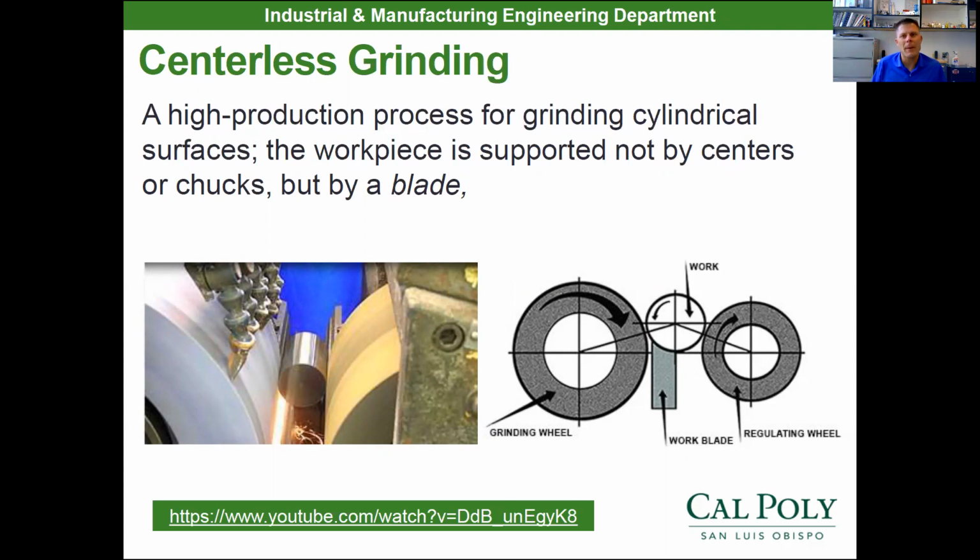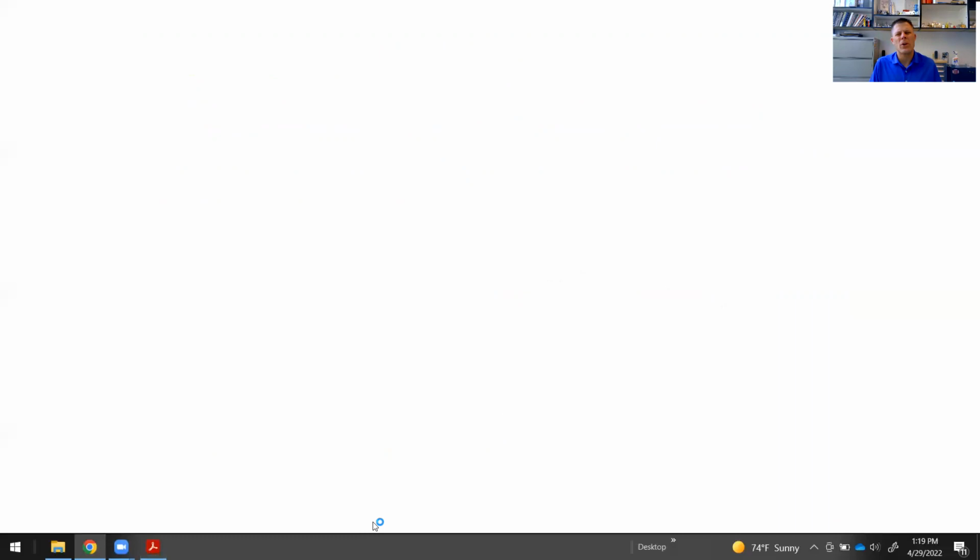Now, we're also going to be pressing in dowel pins to the air motor. Those dowel pins have a plus or minus tolerance of 0.2 on some of them. Some of them are half a thou, depends on what you buy for a dowel pin. But they manufacture that dowel pin for 75 cents with a tight tolerance in the 4 decimal places, 0.2. So I can get a 0.2 tolerance on a pin using centerless grinding. It's a fast process and I can get really tight tolerances. So this video right here is kind of showing you a rendition of it.